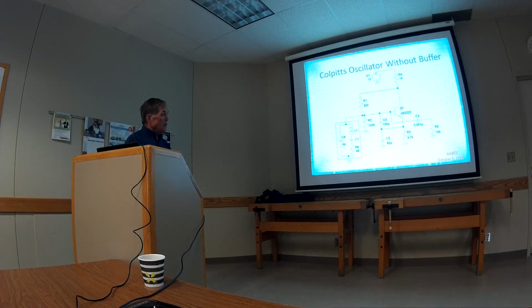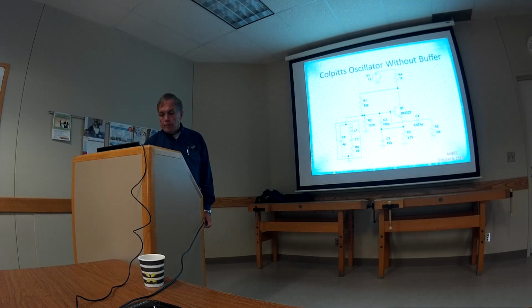You have an inductor and a capacitor. And basically at 7 megahertz there is about 40 ohms of series resistance in it, and about 4 picofarad for the capacitance of the case. So basically, you want to get a resonance between these L1 and C1 to make it resonate at the frequency that you want. And we'll show you how that works.